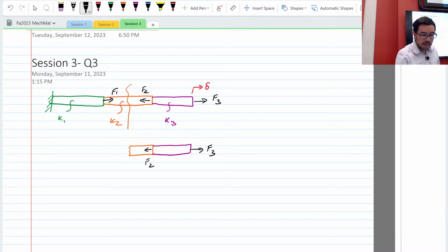and we want to balance, so we use our nomenclature, our internal force, and our convention where we have it coming out. Why is it easier? Because if you do it from this side, I had to figure out what the reaction force of the wall is on this system. So first I had to do external equilibrium, which is fine, but I'm just trying to skip a step.